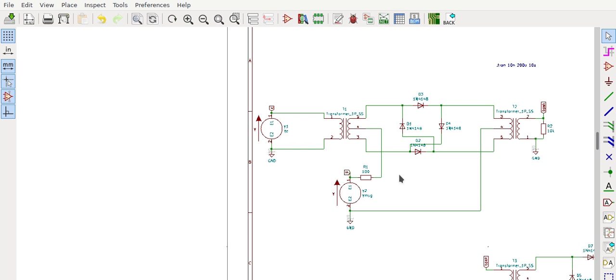When the symbol is 0, we are going to generate a -1 volt here and a 0 volt here. So the DC -1 volt will forward bias these 2 diodes and reverse bias these 2 diodes. Effectively, this node of this transformer will be connected to this node, and this node of the transformer will be connected to this node. So it's basically cross connecting.